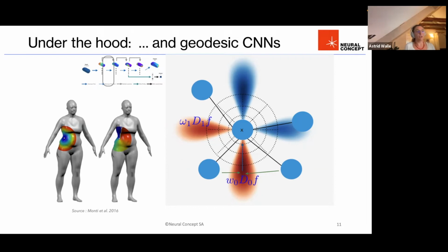And with these local coordinates, we can again define this patch operator, which can go from vertex to vertex and calculate some convolutions or other calculations similar to image recognition, and by that calculate specific features which represent this geometry. In the end, this leads to a translation of this two-dimensional surface mesh into a space where we have the number of vertices times the length of the feature vector that we have just calculated. So you have created a matrix of numbers representing your shape.